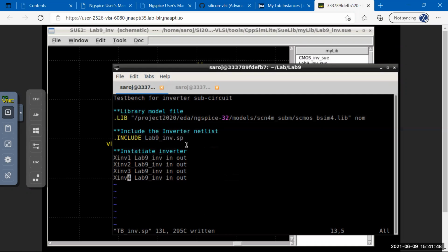So you can see the power of a subcircuit: I didn't have to copy 4, 8 devices, start connecting them, make errors and all that. All I did was just instantiate it. It's just like putting a device, like an IC on your breadboard. It's just like that. But for now, we'll just keep it 1.